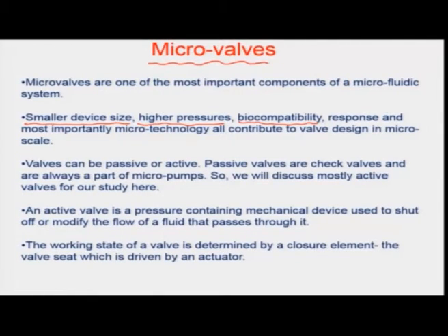So, there are biofluids, and whenever there are biofluids, there is a question of interaction with the surface across which such fluids would flow. Then there is also a question of what is the rapidity of response, whether it is very fast, whether it is able to actuate, block, is it an analog control or a digital control. So, these aspects are again discussed, and most importantly the microtechnology that is involved in contributing to the overall valve designing in the microscale is again another very important aspect of microvalves.